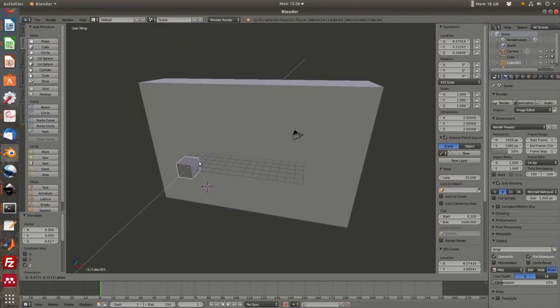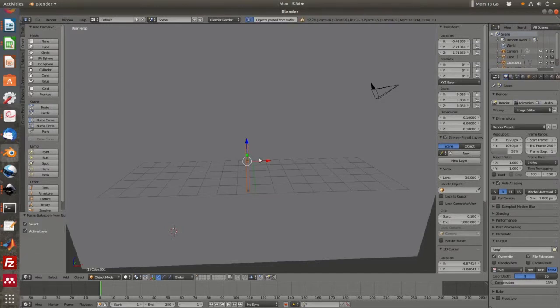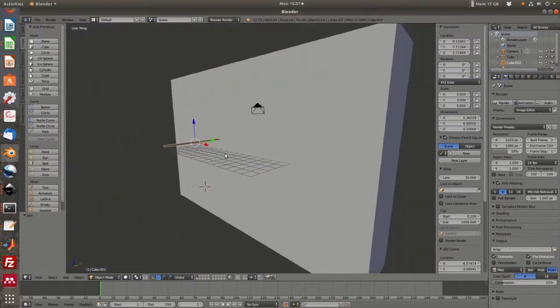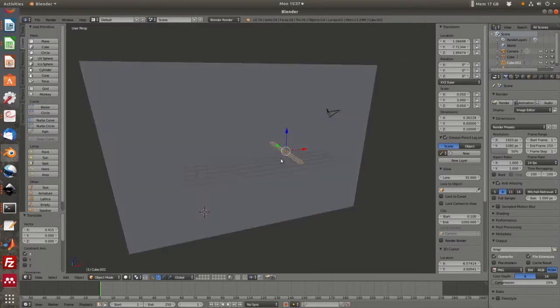The second thing we want to do is to create the electrode itself. So we can start with a cube again and then adjust this to the correct dimensions. We're going to go with 0.1 by 6 for the length and 0.1 again for the diameter. Then I want to make a copy of this because we're going to create a bipolar electrode, and then we're going to join these together. And then we're going to use these to create an indent into the tissue cuboid itself.